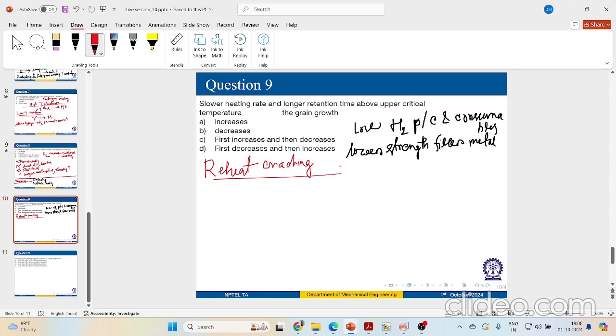Okay, so if you have no question, we'll be talking about reheat cracking. That is also a well recognized problem in low alloy ferritic steel that contains chromium, molybdenum, vanadium, tungsten to enhance corrosion resistance and elevated temperature strength, right?